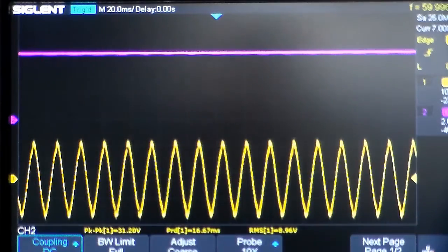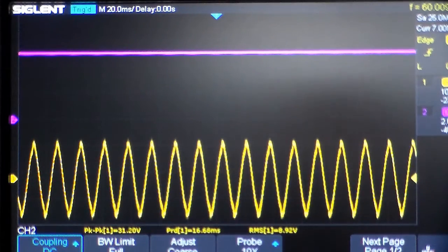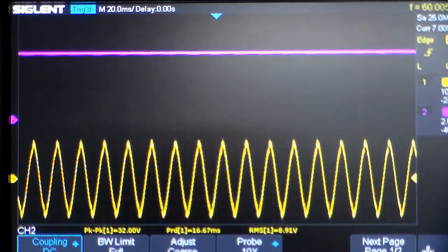One thing I did want to add about DC power, and it's batteries. A lot of people get under the misconception that a bigger battery just means more voltage, and it doesn't work out that way. If you think about it, a little watch battery can be 3 volts, where a big flashlight battery is only 1.5 volts. So the size has more to do with its ability to last and provide current.